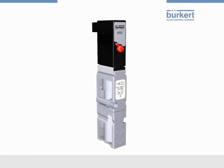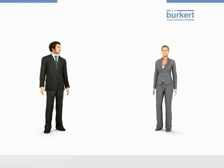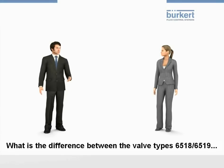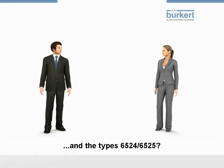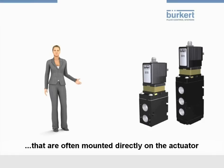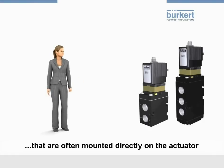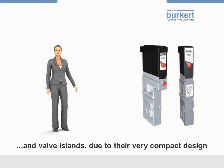Now, Tom and Lisa have prepared some questions. Lisa, I have a question for you. What's the difference between the valve type 6518 and 6519 and the type 6524 and 6525? The types 6518 and 6519 are single valves that are often mounted directly on the actuator. The type 6524 and 6525 are mainly used on valve blocks and valve islands due to their compact design.